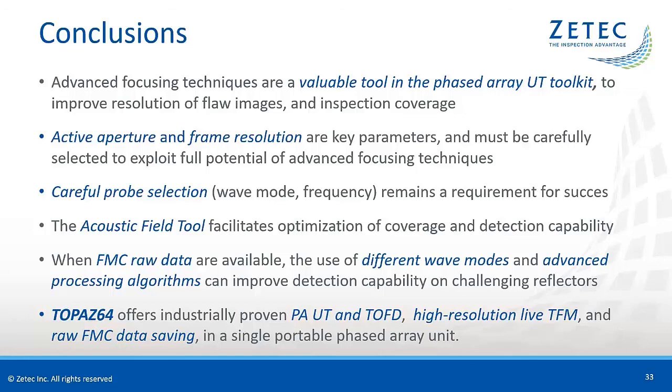The acoustic field tool on the Topaz family of portable phased array units facilitates optimization of coverage and detection capability for phased array and TFM inspections. When raw FMC data have been collected, the reconstruction of different wave modes with advanced processing algorithms in UltraVision Classic can improve detection capability on challenging reflectors.